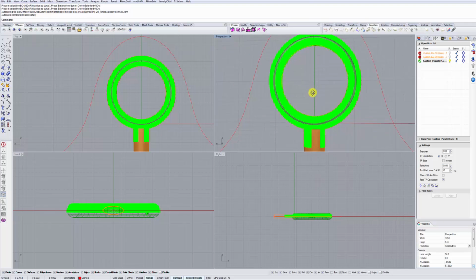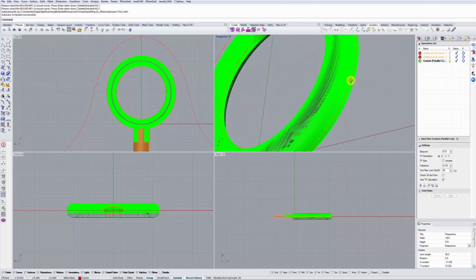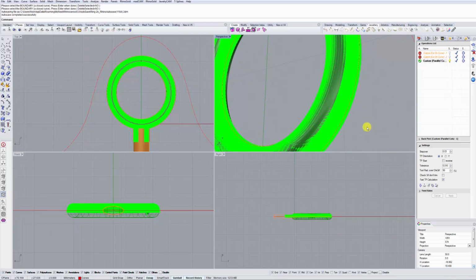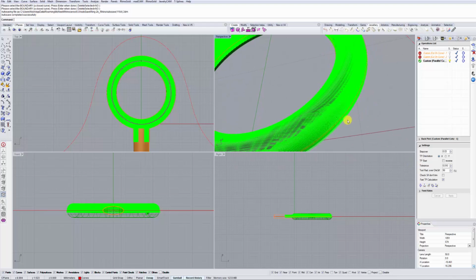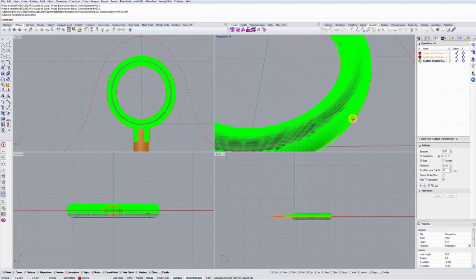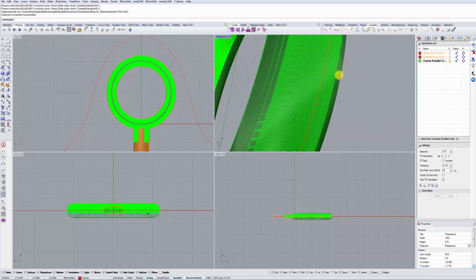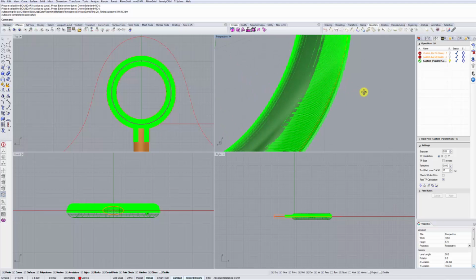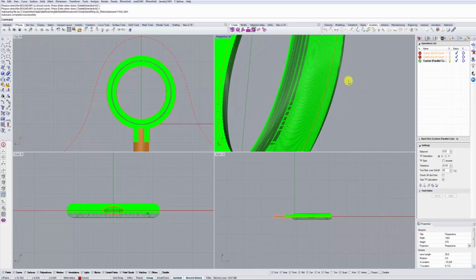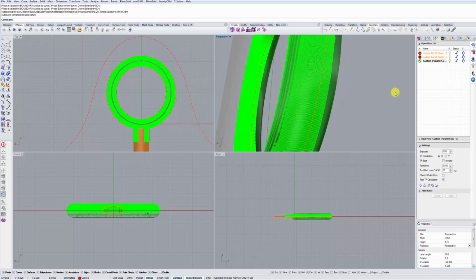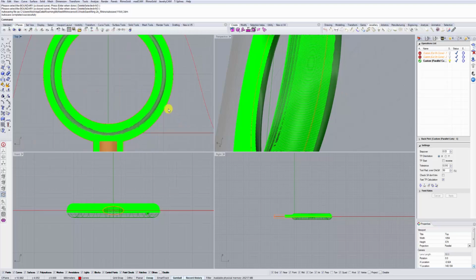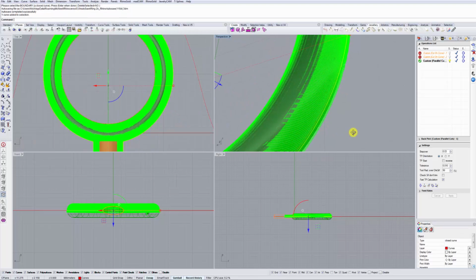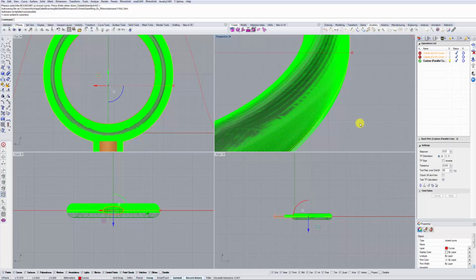Now, one more thing that we can do, although in this case it's not really applicable, is that we can specify a boundary plane or boundary surface. So here you can see that we're cascading up to this point on the model, and if our toolpath was way out here, we would be cutting down potentially even lower, kind of waterfalling off this model quite a fair ways. In order to avoid that, we can add surfaces that we'll add as a block.